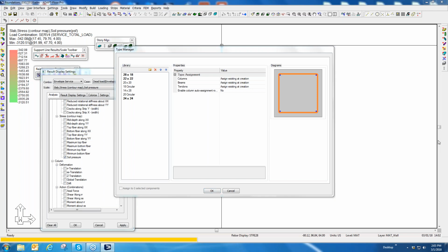The question is, how about a pile raft foundation? We must give spring, area, soil, and spring point, because we have to make sure that the reaction at spring point is not exceeding the bearing capacity, and we have to make sure the contour displacements is the same as the geotech settlement calculation. So I think what you're asking is, can we combine point springs with a different thickness or a different stiffness than area springs?